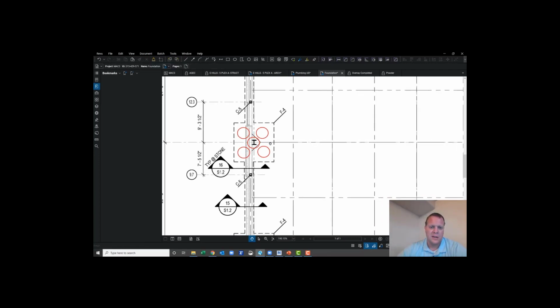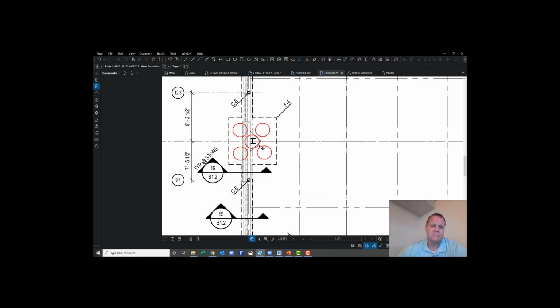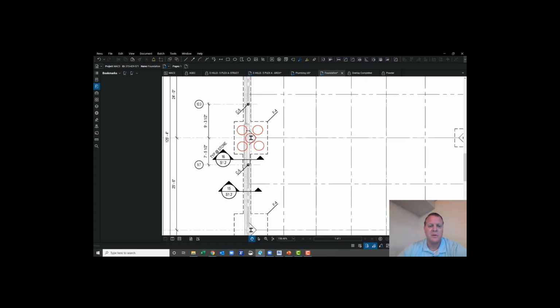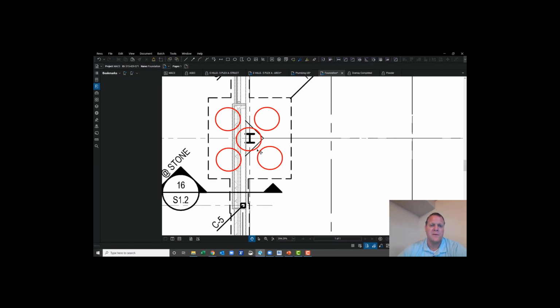This is in the Salt Lake Valley, and so this is most likely part of the frame maintaining lateral loads, right? So this is part of the seismic requirements of the building, or the seismic design of the building, to have this kind of column and not just a tube steel, right? There's a tube steel right there. This is H, so this is probably a brace frame. I didn't look it up, but this whole frame right here is going to be taking care of lateral loads, which also means the rebar in this footing is going to be more, which means there's also going to be bigger bolts for this column. All that equates to not enough room for this pipe to get into this below the footing and out.